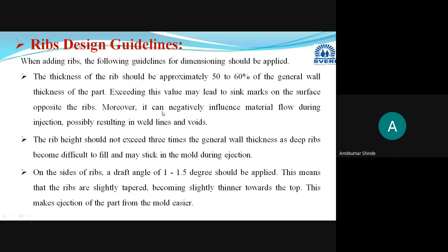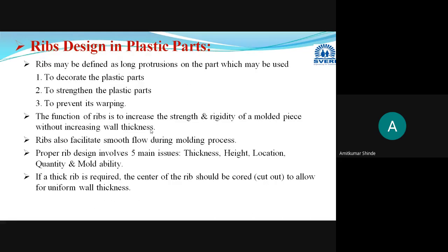Okay, whichever points I have collected here in the design guidelines, the ribs design guidelines, I will explain with the help of a diagram. I will just go through it, and after that I will show you in the diagram. Instead of providing a single rib, go for a number of ribs with minimum thickness possible.